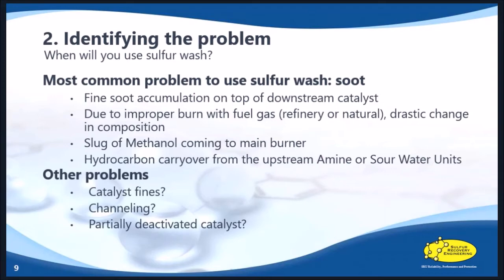But we have made suggestions to clients who have come to us and said, well, I have these catalyst fines that are accumulating, I have this channeling that's happening, I have this deactivation that's occurring, but I don't know what I could possibly do to remedy the situation without having to shut down. I've in the past mentioned they could try a sulfur wash to remedy these problems other than the soot. Now, I should indicate that even though the potential is there that the wash can remedy these, I have no testimonials myself of them using the procedure or any successful stories of it being used in those situations. But if you want, you can ask me questions later on.